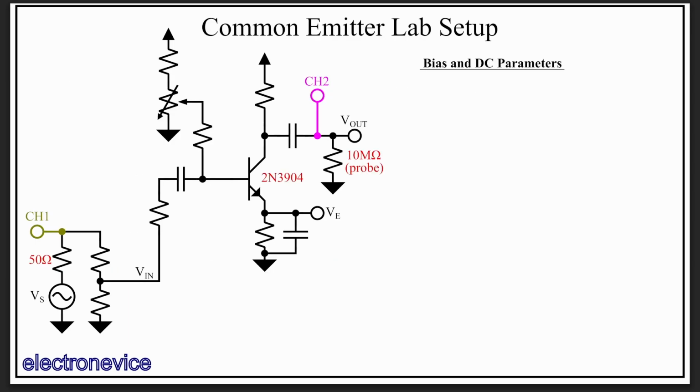So here's the circuit, but with most of the values not yet written in. We have a function generator with a 50 ohm source impedance going into a resistive divider. The output of this divider serves as our input voltage. The reason for the divider is to make the input voltage a very small signal. This is important because we're going to design in such a large gain, and so we'll need a small input signal.